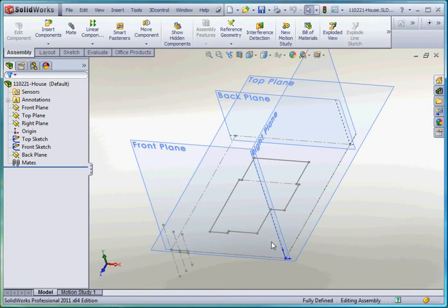The top plane is going to be associated with all the features that are going to be defined with the footprint of the house, and it actually defines the very top of the subfloor of the house, and the floor is actually built below that, and we'll talk about that a little bit later in some subsequent videos. The right plane's established, the front plane's established, we created the back plane, and now I'd like to create the left plane, and it's very simple to do that, and this will complete our modeling box if we do that.